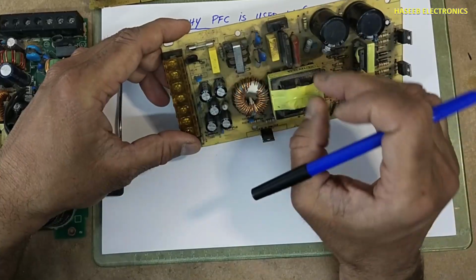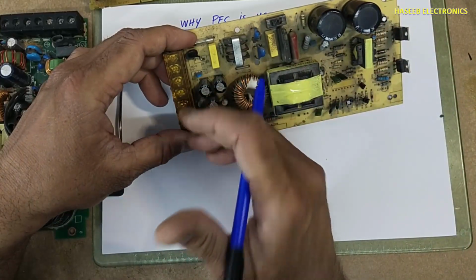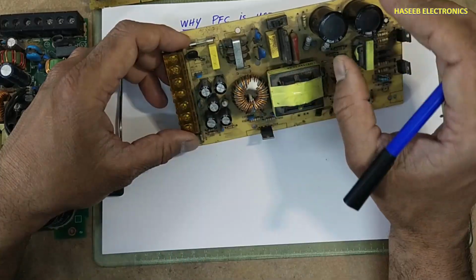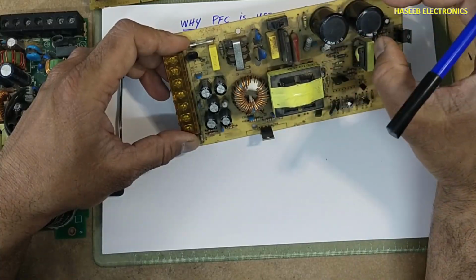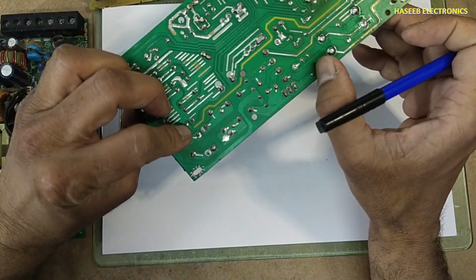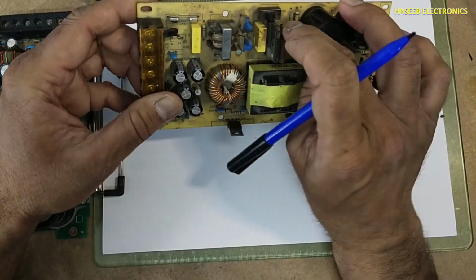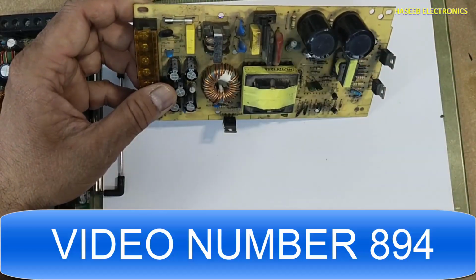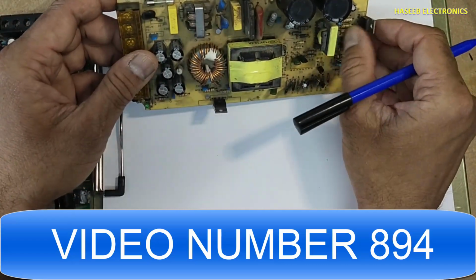Why do we need this switch? Because we are taking approximately 250 watt output, 12 volt 20 ampere. At that time we need some regulated voltage on this line. Basically this switch puts these capacitors in series and parallel. I already shared a video on why this selector switch is used. You can watch that video as well. The number is displayed on the screen.